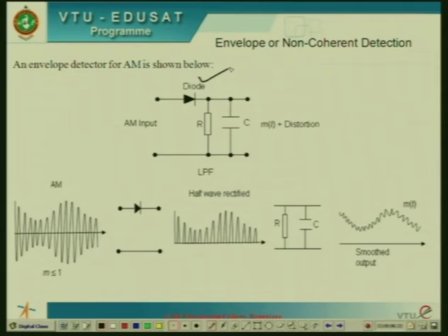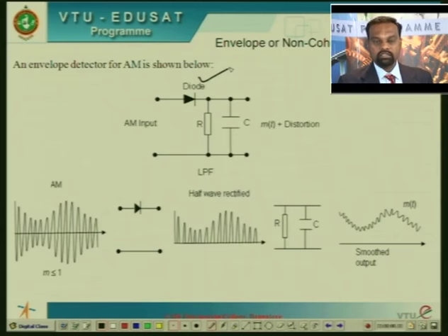If you apply a voltage to the input at the anode, the diode is forward biased if the voltage is greater than the cut-in voltage of the diode. Once the input is more than the cut-in voltage, the switch closes, so input will be equal to output. If the input voltage is less than the cut-in voltage, the diode will be switched off. That means the switch is open circuited, so output will actually be 0.